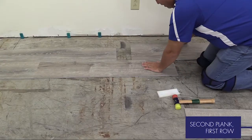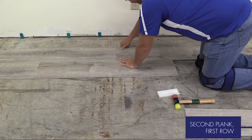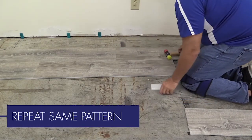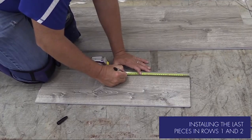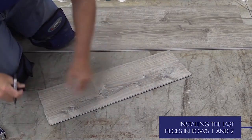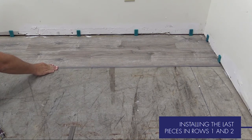Position the long groove of a full plank into the tongue of the second plank in the second row, then press, tap, and square as before. Repeat the same installation pattern on rows 1 and 2 until you reach the opposite wall and cannot install another full plank. Cut the pieces to fit, being sure to maintain the expansion gap and install as before. Then move the entire assembly against the spacers on the starting wall.